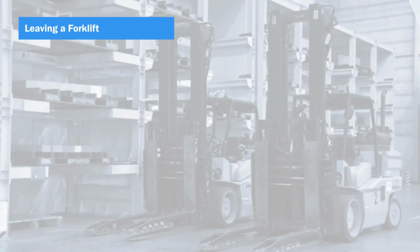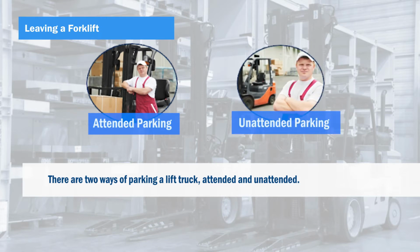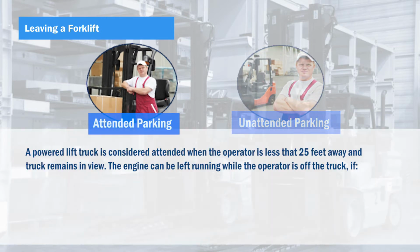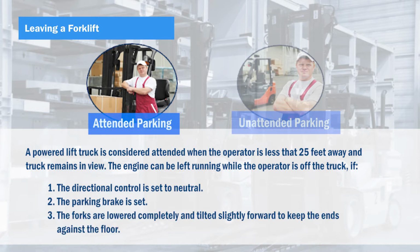Leaving a forklift. There are two ways of parking a lift truck: attended and unattended. Attended parking. A powered lift truck is considered attended when the operator is less than 25 feet away and the truck remains in view. The engine can be left running while the operator is off the truck if the directional control is set to neutral, the parking brake is set, the forks are lowered completely and tilted slightly forward to keep the ends against the floor.